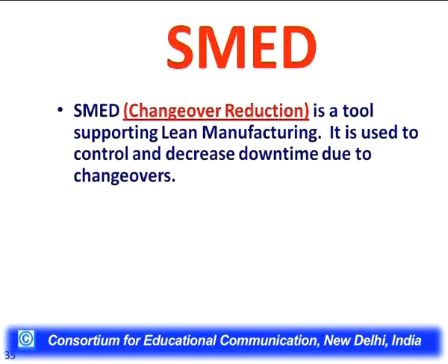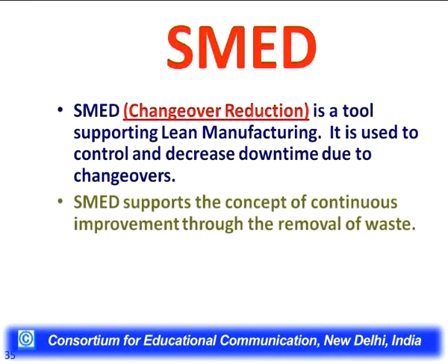SMED, single minute exchange of die. SMED, changeover reduction, is a tool supporting lean manufacturing. It is used to control and decrease downtime due to changeovers. This particular SMED is part of lean manufacturing, lean operations, or just in time. SMED supports the concept of continuous improvement through removal of waste, and this waste is wasteful activities, and these will be visible only if we map the existing process, analyze it thoroughly, and suggest modifications for reducing the time.